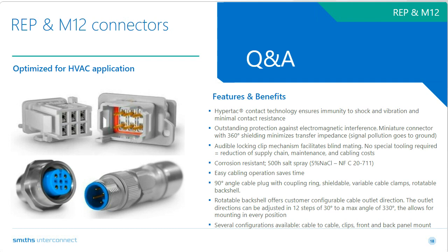I talked about the galvanic corrosion that it initiates. And particularly when you are in a high humidity environment like 50 or 60%, that failure mode is ever so accelerated. And what that means, other than the material properties deteriorating, is it sets in well and truly the increase of contact resistance.